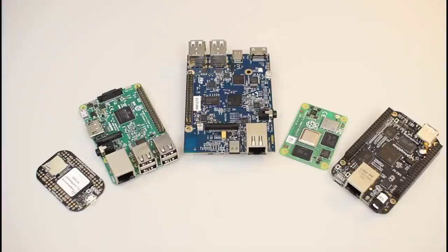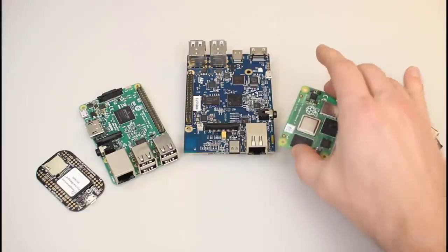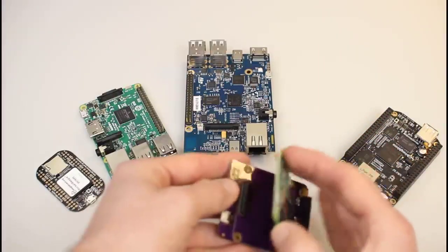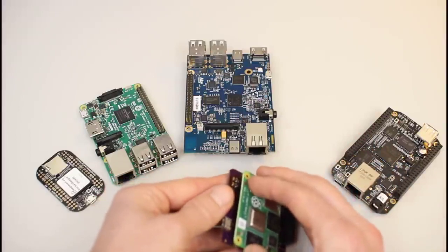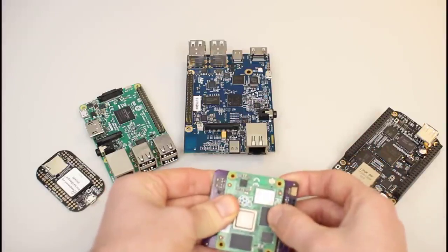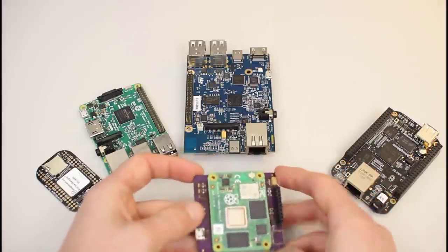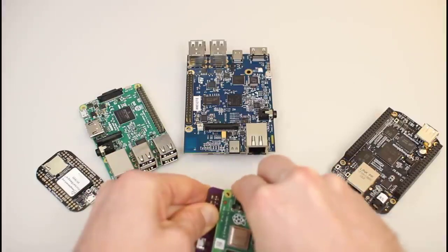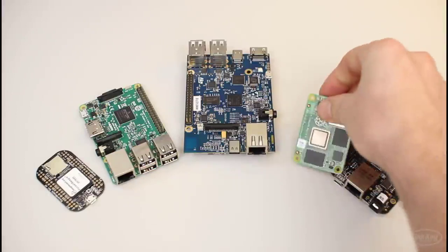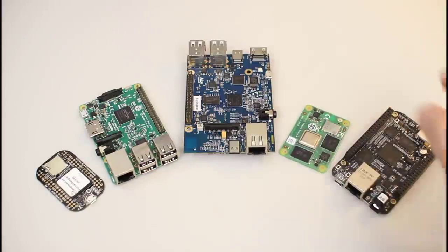Note that creating your own custom single-board computer is extremely difficult. The PCB might be complex, but it also means finding or creating drivers for every piece of hardware found on the board, like RAM, USB, and Wi-Fi. Because of that, some vendors offer reference boards that you can copy, or even systems on a module that you can design a custom carrier board around.